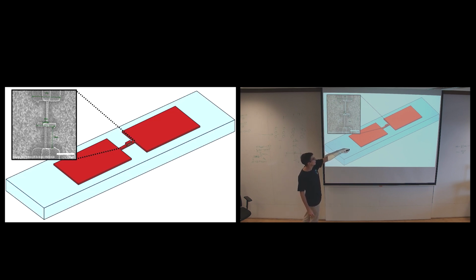And in between this overlap, the yellow thing is the oxide barrier. So we deposit the aluminum. This is sapphire, this is aluminum deposited. Then we grow some oxide, and then we deposit the second layer of aluminum. And in the middle, we have the junction. So this is a real qubit we use. And I think Alex was telling you about the scanning electron microscope and so on yesterday. This is taken with a scanning electron microscope. Of course, this is too small to see with a normal microscope. So you basically shoot electrons and then you measure the electrons back, just because they have a smaller wavelength.